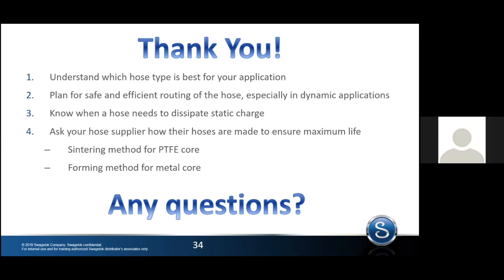So it is FDA approved. Great. Cody, you had a couple questions there that you came across? Yeah. So, Doug, if you subject an all-metal hose to gas pressure impulses, does it perform better than if you subject it to liquid pressure impulses? Yeah, good question. Liquid is the worst. Similar to what you might know in your own plumbing, like water hammer. Liquid impulses can be very, very dangerous on a metal hose. So gas, obviously, is compressible. So the gas impulses will have less of an impact, but it's still not the best for metal hose.